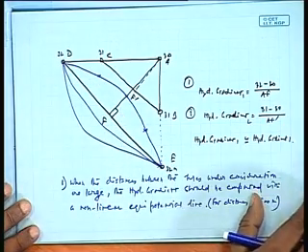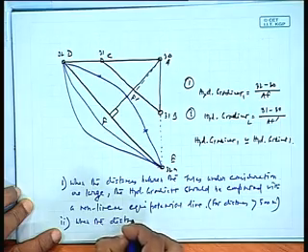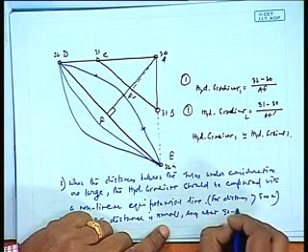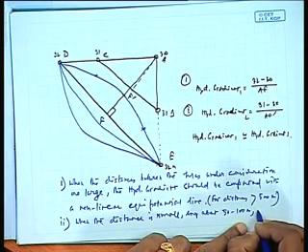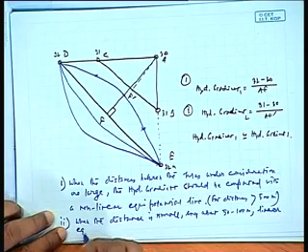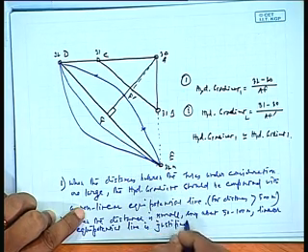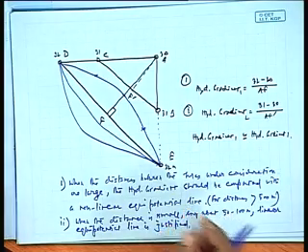Otherwise, when the distance is small, say about 50 to 100 meters, a linear equipotential line is justified. So essentially it becomes an engineering decision as to how to compute, but the method of computation remains the same, that is, the change in the water head divided by the distance. In almost all cases, it is the perpendicular distance that is under consideration. That has to be a perpendicular distance.